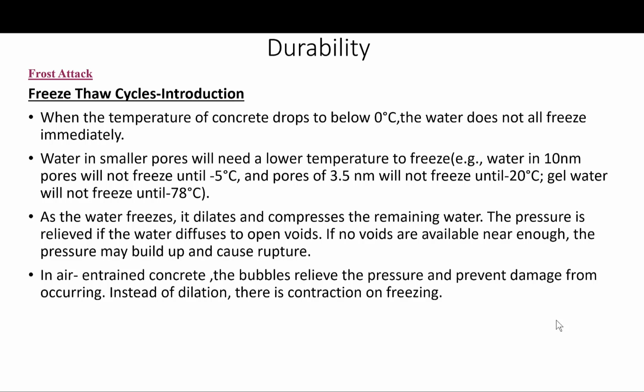So even when the freezing temperature is reached, a significant portion of the water in concrete will supercool rather than freeze, since a seed or nucleus, an ice crystal, is required to initiate the formation of ice. The seeds will form on the exterior of the concrete and in large voids within the concrete, penetrating into the body of the cement paste as the temperature drops. The crystals do not easily penetrate small capillary pores, and can do so only when the temperature drops well below 0 Celsius. Finally, the water absorbed on the surfaces of the calcium silicate hydrate, which forms on the surfaces of the capillary pores, will never freeze, although it may migrate to the capillary pores where the ice has formed.